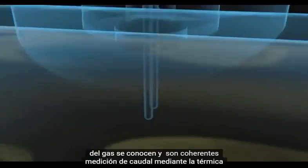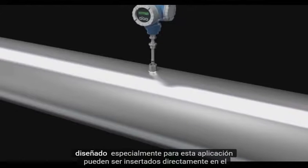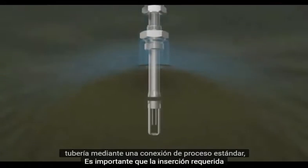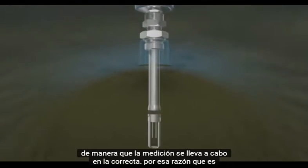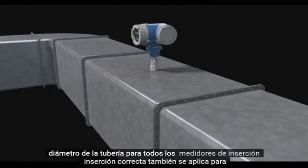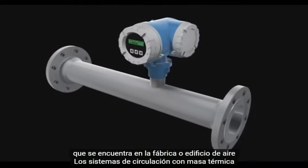Flow measurement using the thermal principle is also possible in large pipes and ducts. There are meter types designed specially for this application. They can be inserted directly into the pipe via a standard process connection. It is important that the required insertion depth be respected so that the measurement is carried out at the correct point. For that reason, it's essential to program the actual internal pipe diameter for all insertion meters. Correct insertion also applies for rectangular and square ducting, often found in factory or building air circulation systems.